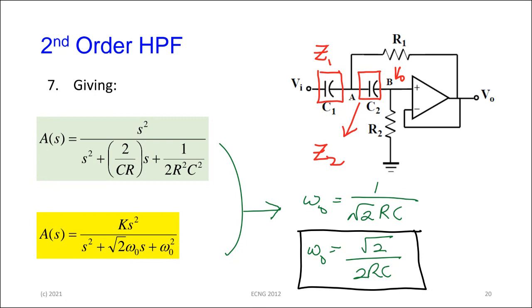Okay, so two different approaches were taken here. You could use either one. There's a standard form for the low pass as well, which we know, which is what we did in signals, and we just showed that. And there's a standard form for the high pass. In both cases, the low and the high pass filter have the same cutoff frequency, but remember the relationships between R and C when you're drawing it.